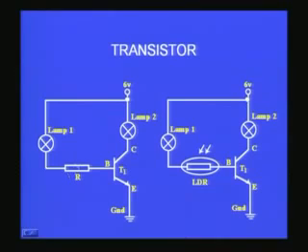Now if I increase the value of the resistor, you would find this lamp will not show a very significant change in intensity. But when I increase its resistance enormously, for example from 100 ohms to 10,000 ohms, this lamp will not even glow, because the current through that circuit becomes very small. But you will still see some glow here, even though it will be somewhat less. That means there is an amplification coming into play, and this amplification is called the beta of the common emitter configuration.